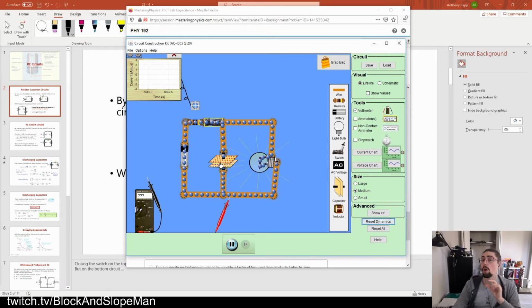And for that brief moment in time, a zero potential difference means that there is no difference between the capacitor being there and just a plain old wire. The picosecond after that, or the femtosecond after that, instantaneously, now it starts to go back down, because now there is a potential difference because of this, and that slows down the flow of charge.